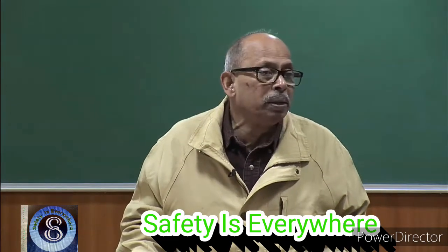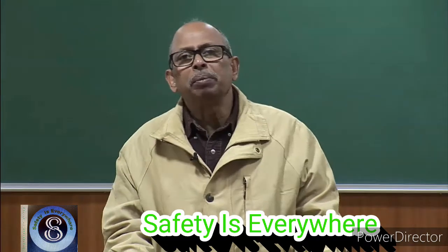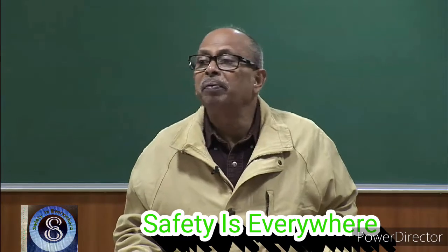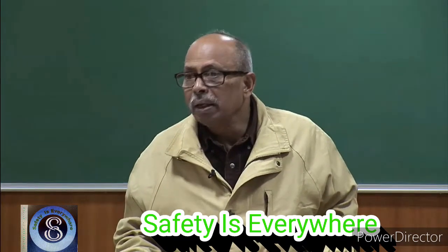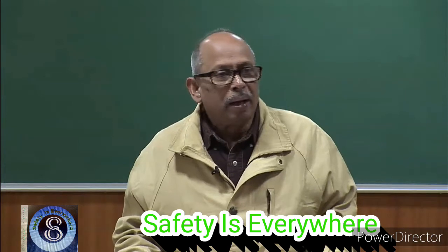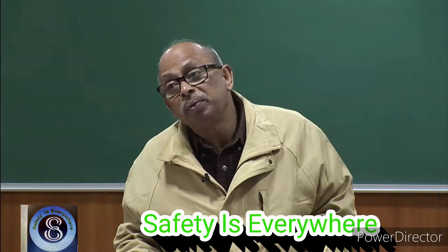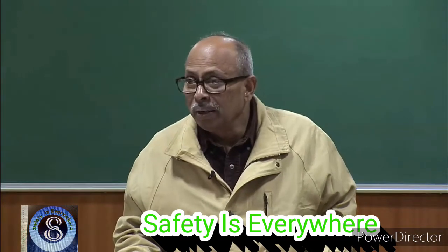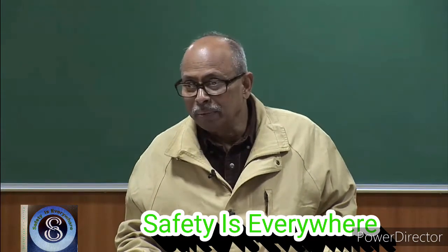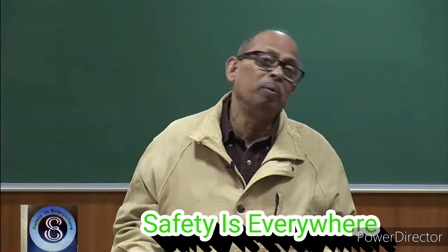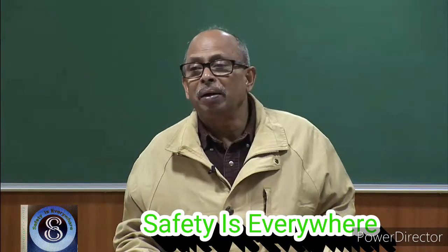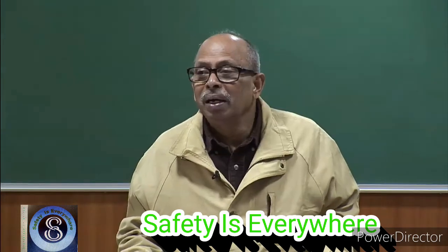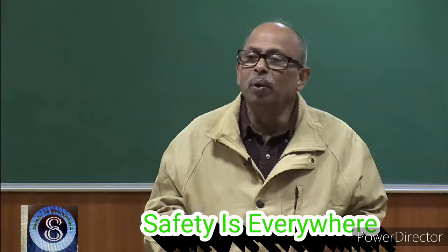Now, it depends upon occupancy class. For example, in a residential building, the type of fire load you will have is different than in an office, right. And in an office again you can have two types of scenario. Today of course things are quite different, but in the good old days you would have a lot of papers. In some other offices you might have all the papers locked up in a steel almirah. So, those will have less. So, fire load is based on that.